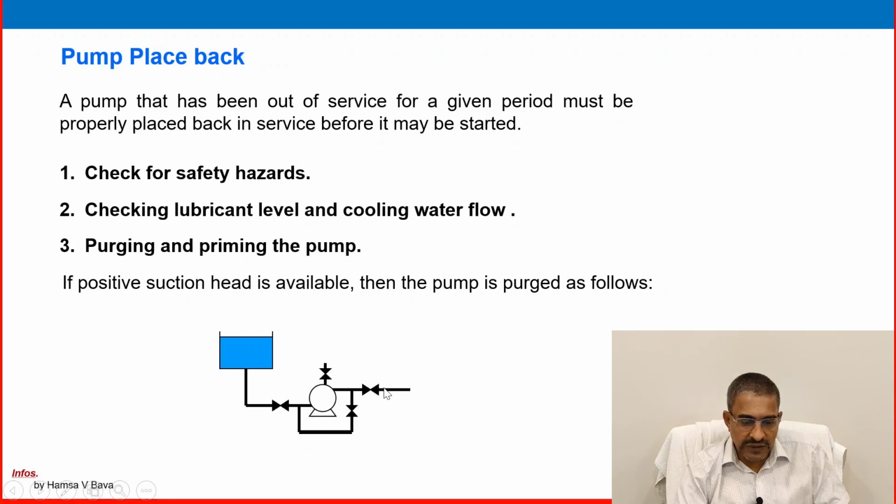So all valves are closed now, and the suction tank is filled with liquid. Now the vent line is open. Whenever you get a chance to visit your area for a centrifugal pump, see how the priming is done. That will give you very good confidence to do the job.